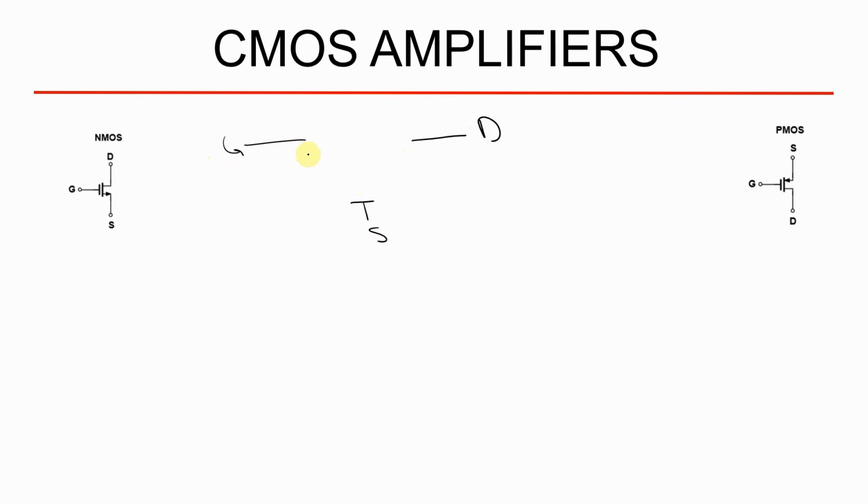For a small signal model, between gate and source, you have to consider VGS, which is a parameter that is varied in every circuit. And there is a dependent current which is called gm VGS. Well, this is gm times VGS. And what is gm? gm is the transconductance for this amplifier, which we can define as